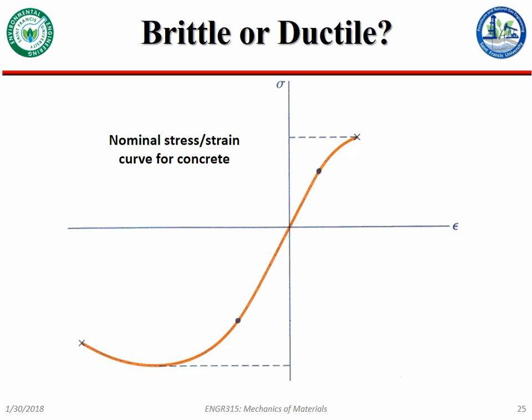For example, this is a typical stress-strain curve for concrete. Now, would you say that this is acting brittly or ductilely? And if you need to caveat your answer, feel free. Option C. Describe option C. It looks like when it's getting stretched, it's more brittle, and then when it's compressed, it is ductile. Okay, which way is being stretched again? Up. Okay, so this is in tension or being stretched. It's usually a positive stress. That means this is compression.